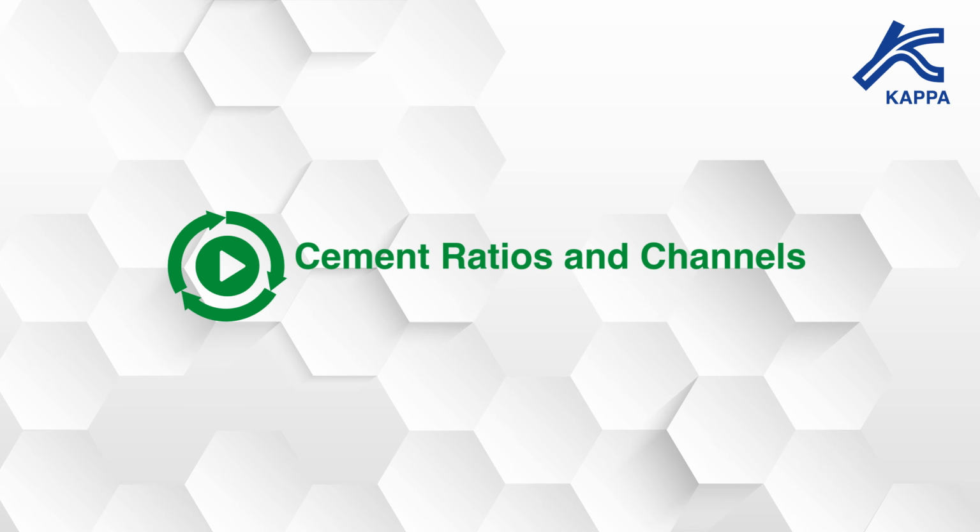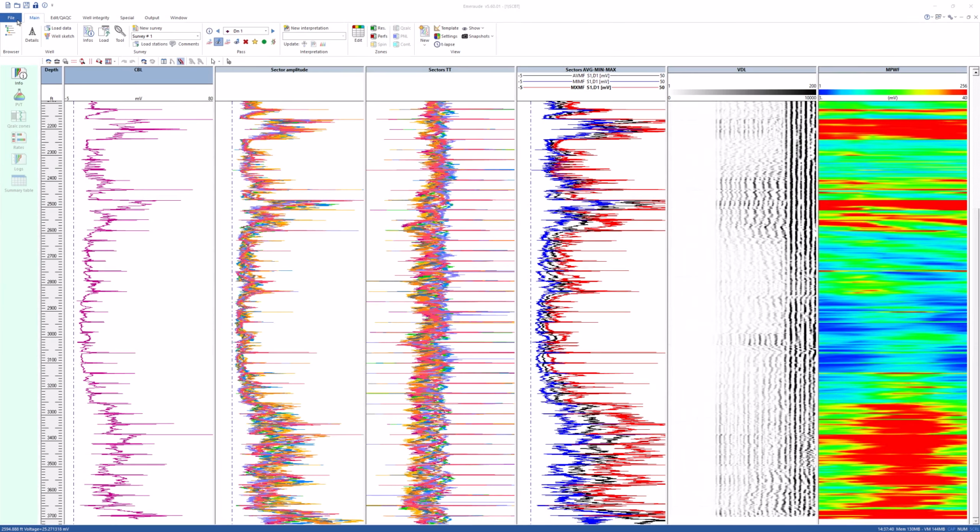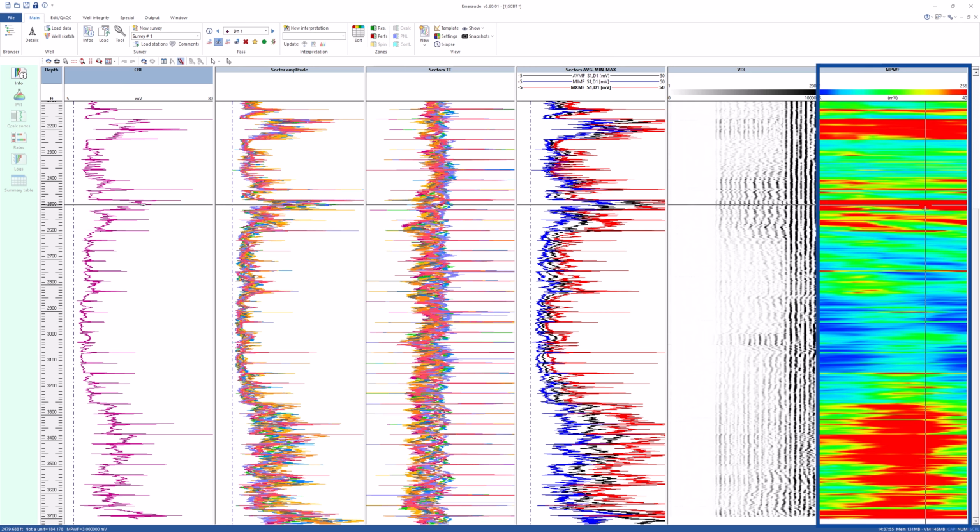Calculating cement ratios and identifying channels. This video shows how to compute cement ratios and detect channels with the automatic identification algorithm. Segmented sonic tools output maps of amplitude for a number of receivers, typically located at 2 or 3 feet from the transducer. This information can be used to detect channels.